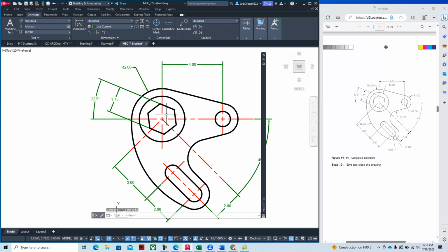And the way that I was taught was to create center lines on a center line layer, not to automatically have them annotated within the dimension style. So it's kind of a thing that the computer programmers thought, hey, this is great, it's efficient, but from a standards point of view, I prefer to stay with the standard of just keeping them on different layers.